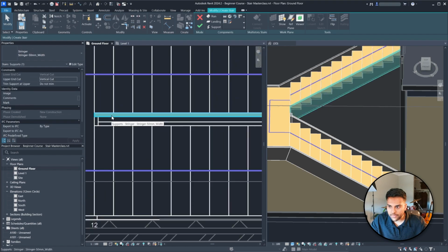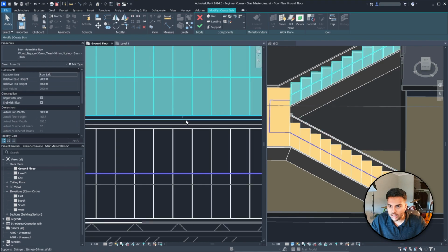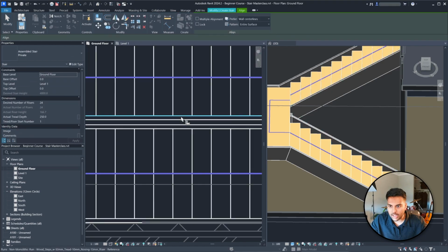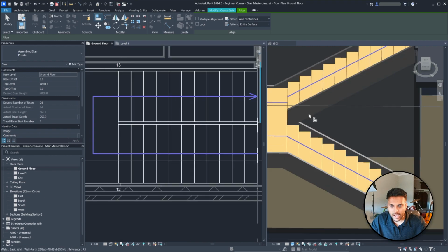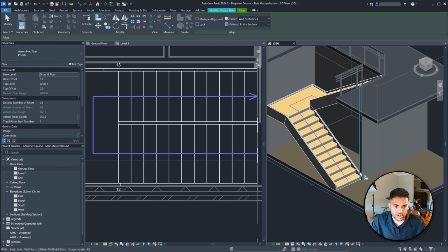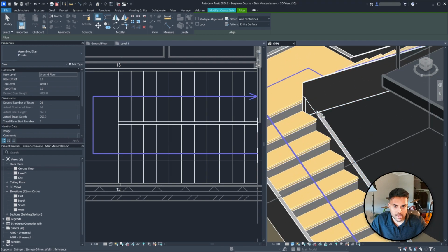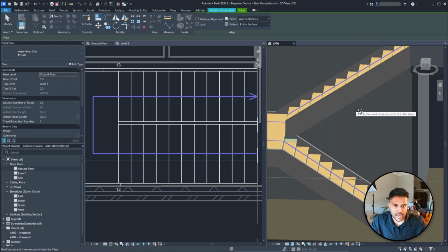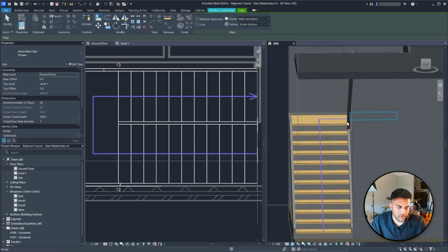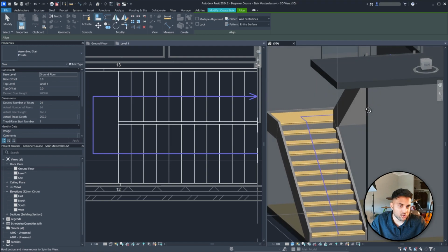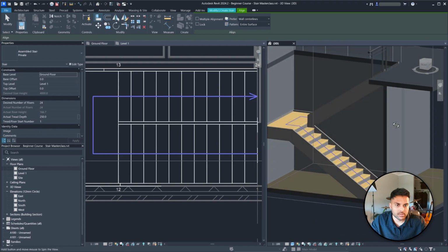And the idea behind this is I'm also going to extend this down so that this is aligned, right? This right support is aligned with this right support. It's going to be on top of each other, and you'll see why in a second. So I'm going to take this and I'm going to go align, and I want to align this to this, and that's going to pull it on top of that. And what you'll see is now you can go up, right? And those two right supports are sort of overlapping each other. And what this means is I can extend my wall this way, just before that right support. And the right support can actually attach to the base of that wall. Yeah?